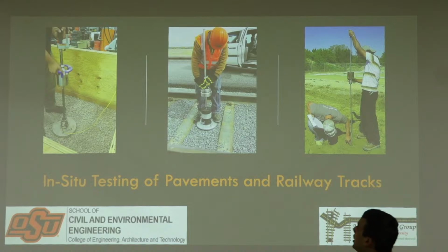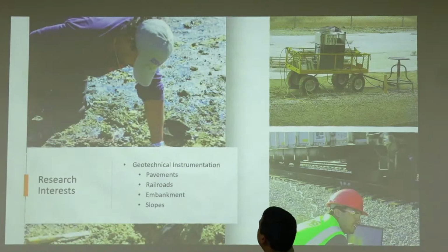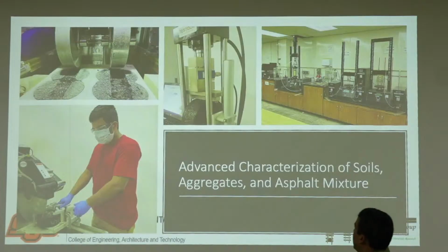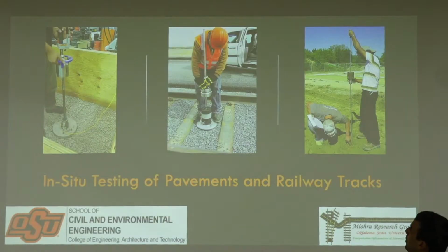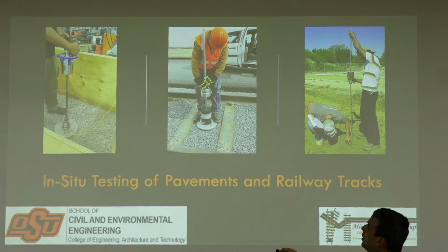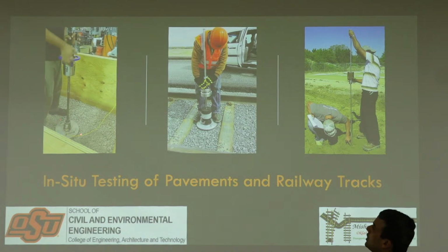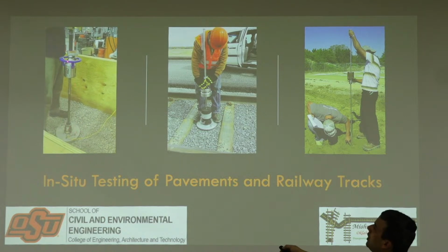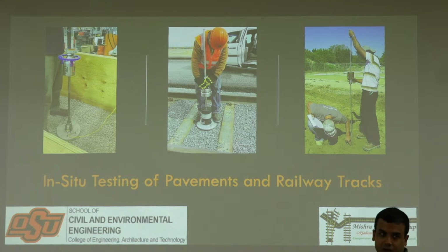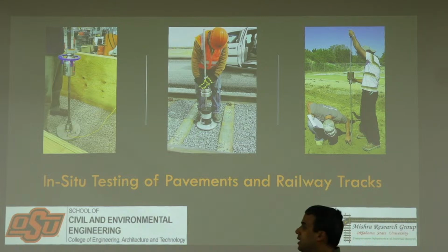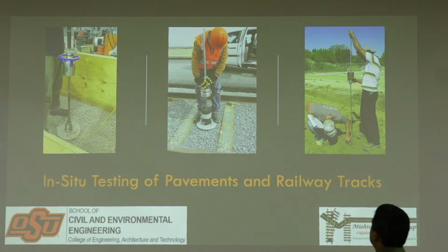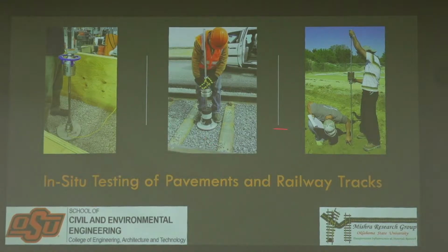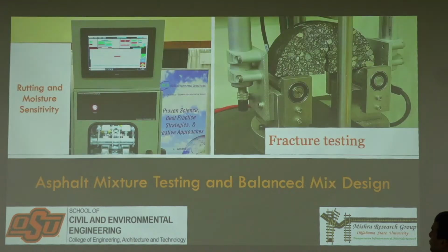So I have been talking about the lightweight deflectometer. This is some instrumentation work. This is the lightweight deflectometer. It's a single sensor in there. There is a load cell, and you can drop it and measure deflection. That actually gives you a good idea of stiffness. That's me testing on some railroad tracks. This is the same as the PhD work for the DCP and so on.